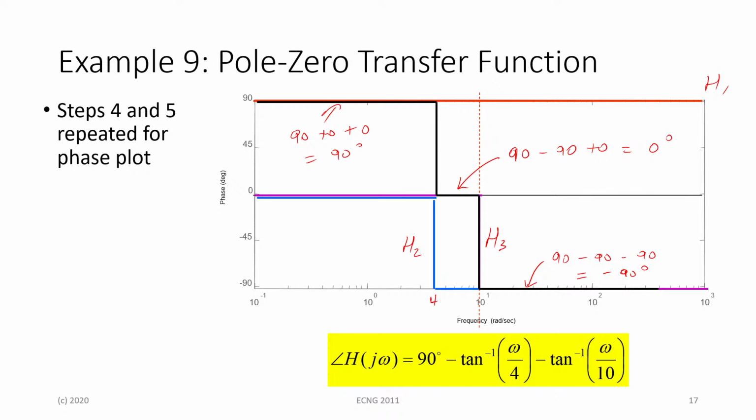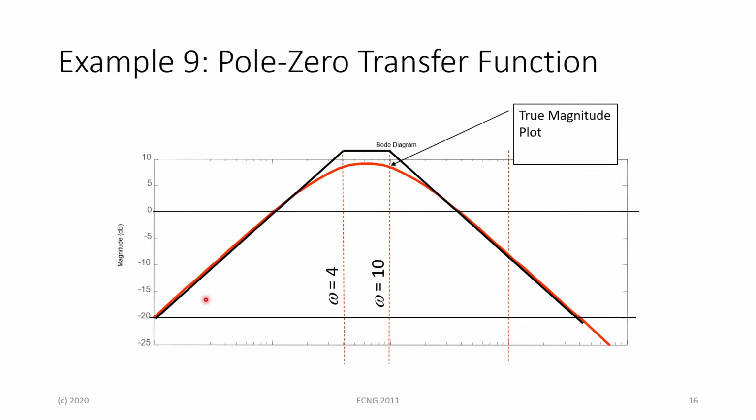There are two corner frequencies for that magnitude versus frequency graph in particular because of the subsystems. There won't be one corner frequency, and the reason for that being is that we saw that the denominator was of order 2. So basically, the corner frequencies here are represented by those pole frequencies, or those pole values.